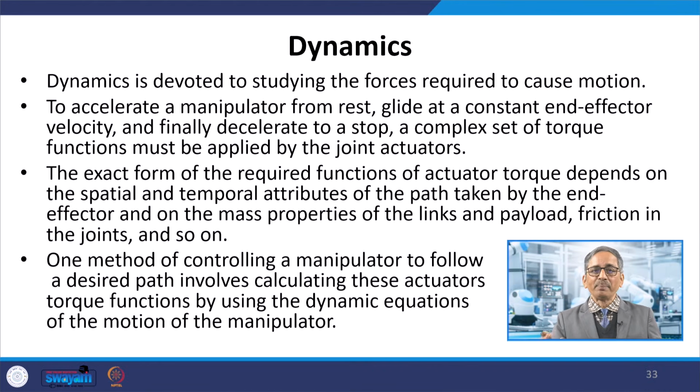The most important part in any manipulator is the dynamics. And the dynamics is devoted to studying the forces required to cause motion. As joints accelerate, or we say the manipulator starts from rest, glides at constant end effector velocity, and finally decelerates to a stop, in this entire operation a complex set of torque functions must be applied by the joint actuators.